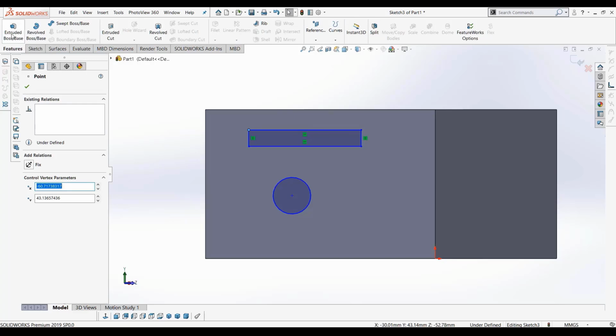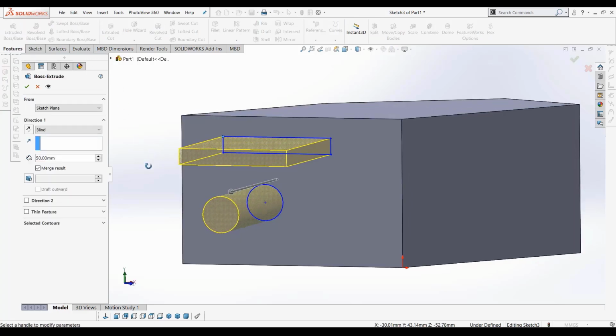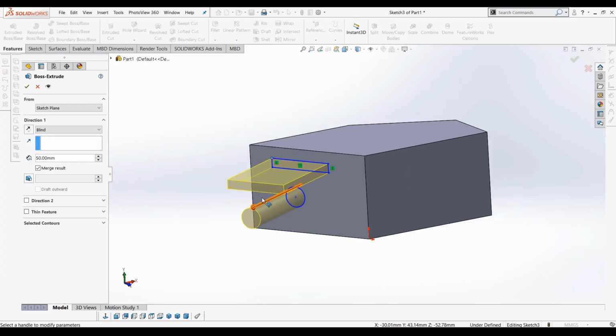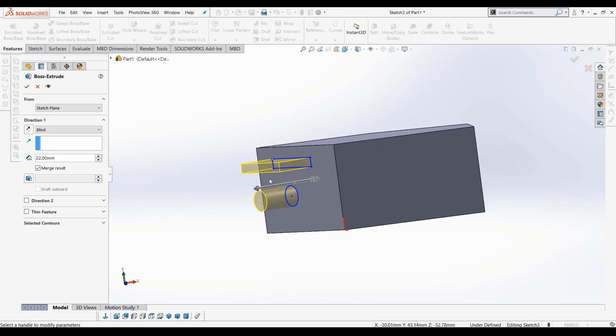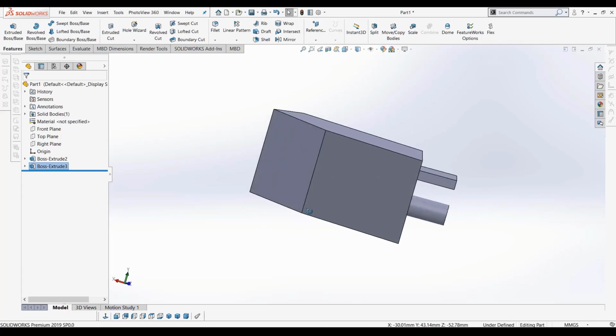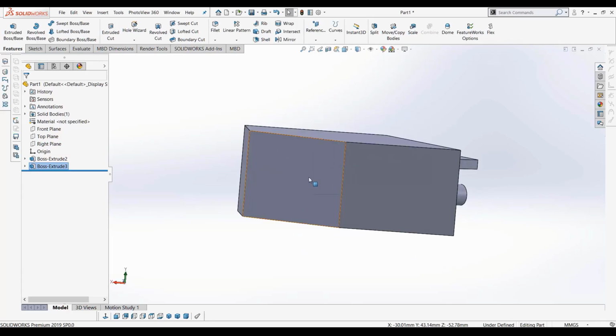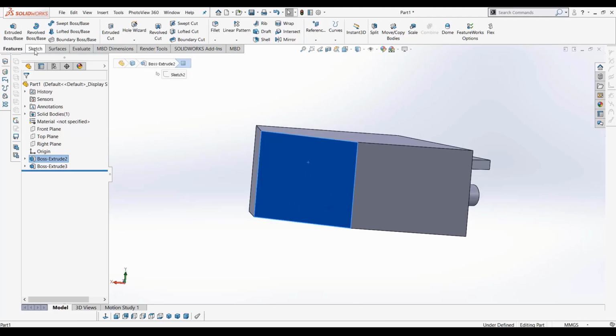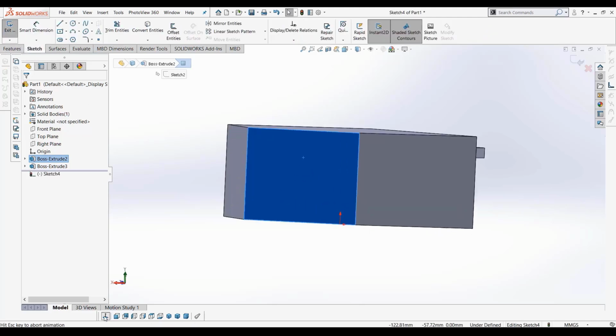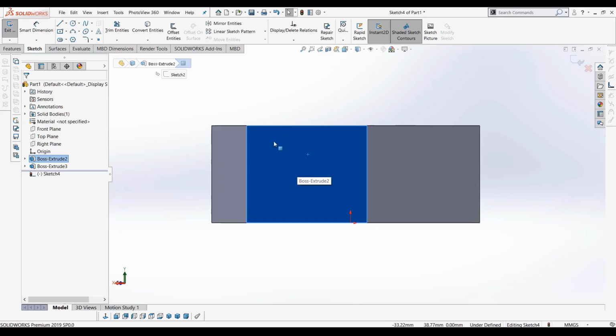I go to the feature and click on Extrude, and you can see that we were able to create a new sketch on this surface as well. What is another mistake that most of you make? It is that when you select this page, click on Sketch, and also hit Normal to view, you think you are limited to this blue area.